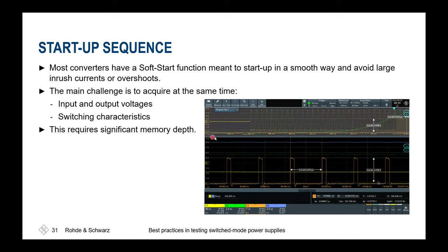A typical startup sequence is shown here: we get the sine wave in the back, which already starts as maybe a clock. Then other consumption at the bottom is shown for a certain voltage level. Ramp up takes place, and all these timings could then easily be measured using cursors, automatic math functions, or maybe also gated measurement functions. That means you're adding different timing gates to do different measurements and see at the end if your supply and your system match quite well together, or if there are hiccups coming up.